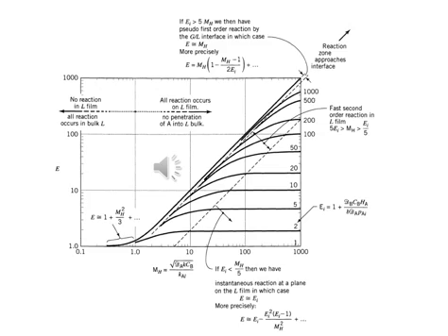The second region is a case where the Hatta number is in between 5 EI and EI divided by 5. And in this case, we determine the enhancement factor from the graph.